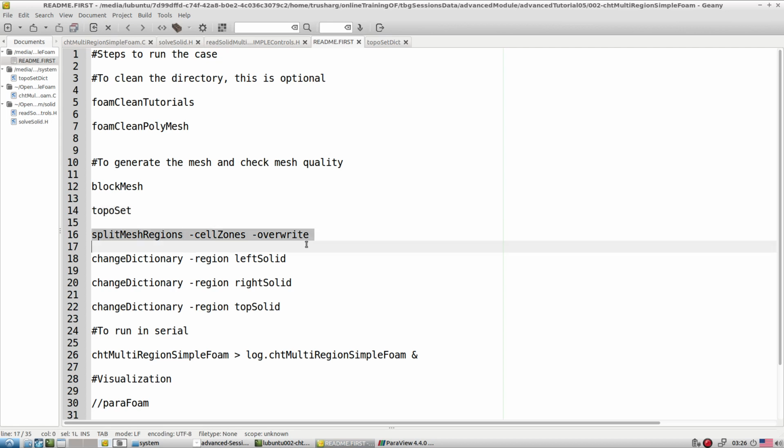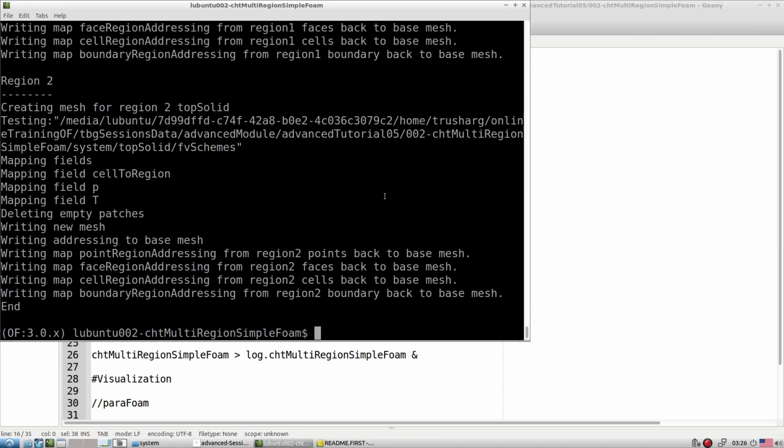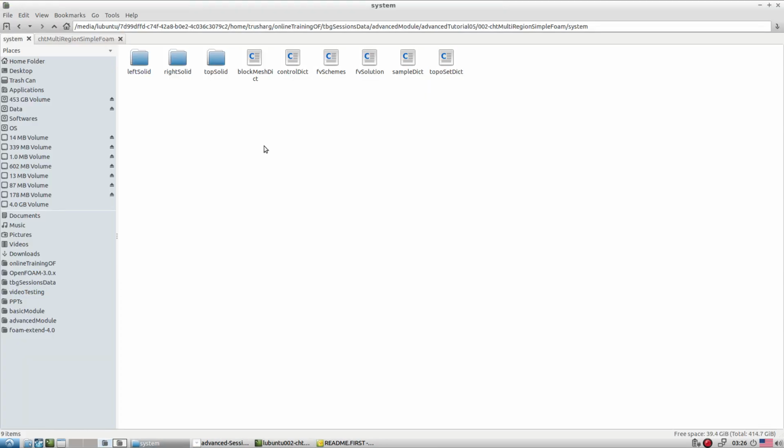Then we just constructed this zone. Now let's split the zone, so we have appropriate cells ready to go. That is the idea we have. So we split the zones, so we have cell zone 1 2 3. So when you say cell zone 1 2 3, what is going to happen? Inside the 0th folder it also tries to generate all these 3 folders. That is what one can look at from here.